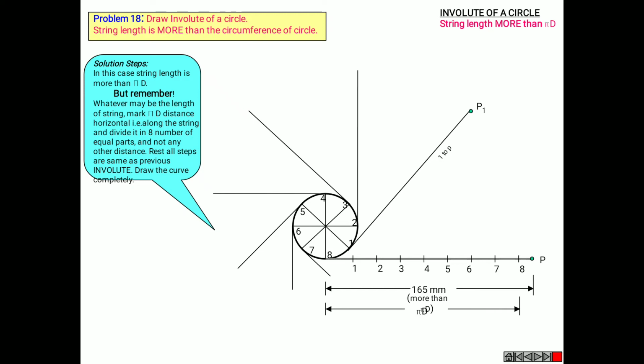So now same from 1 to P, mark the point on the one tangent line, same 2 to P on the second tangent line, repeat the same from 3 to P, 4 to P and so on to all the tangents.